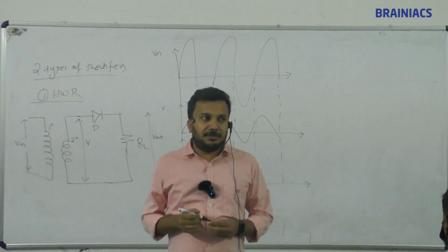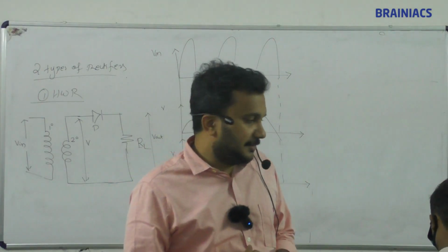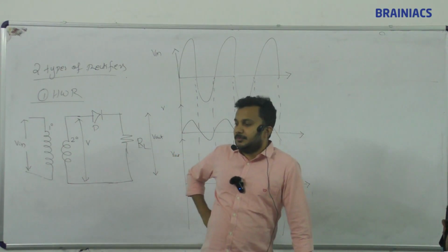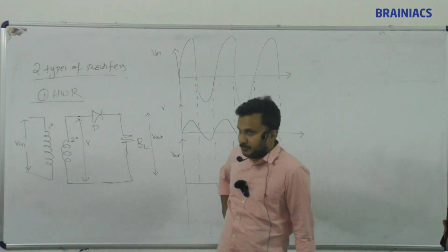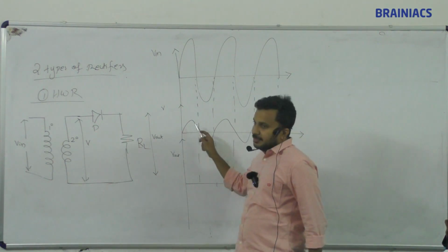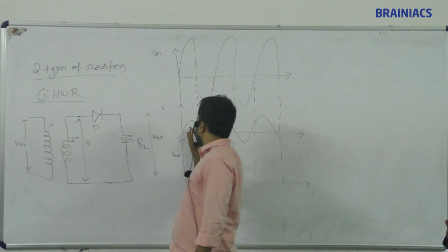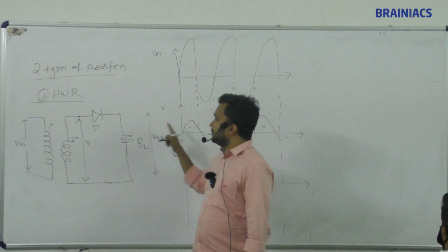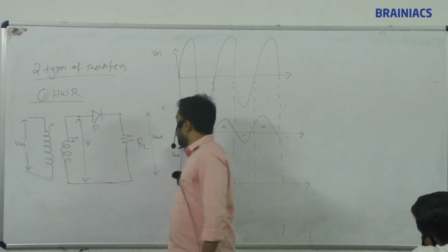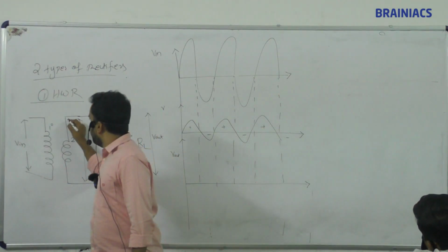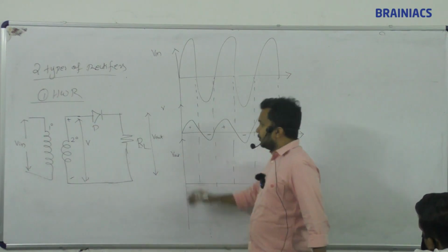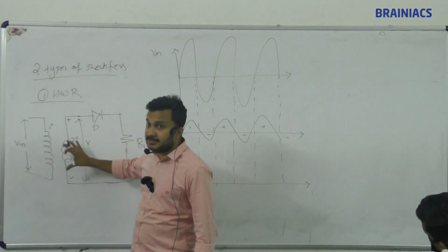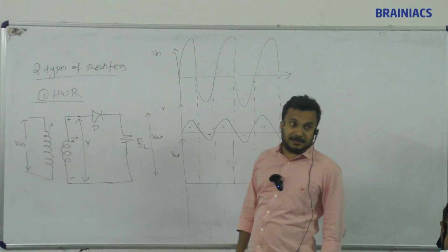Because we cannot give high voltage to the diode, it would affect its lifespan, so we step down to the next level of voltages. Okay, next what happened? See here, we have two cycles, positive cycle, negative cycle, positive, negative, positive, negative, and so on, and it continues. Whenever a positive cycle comes, what will happen? For the first positive cycle, here it is positive, here it is negative. Positive cycle means the upper end connection is positive, then the next connection is negative. Only then will the voltage be generated.